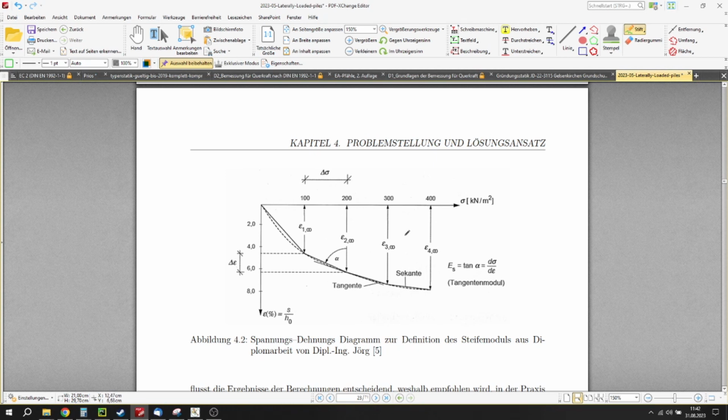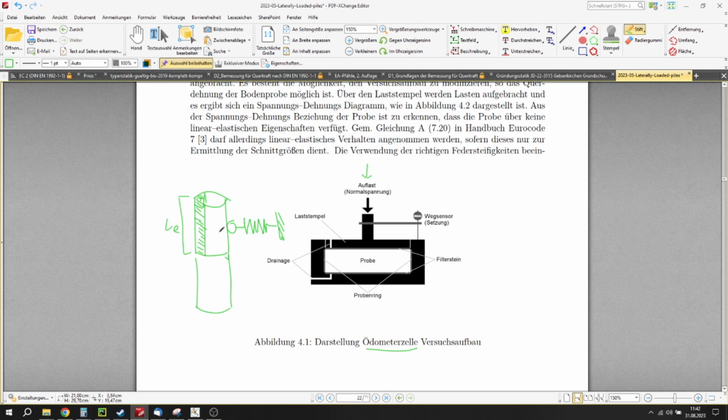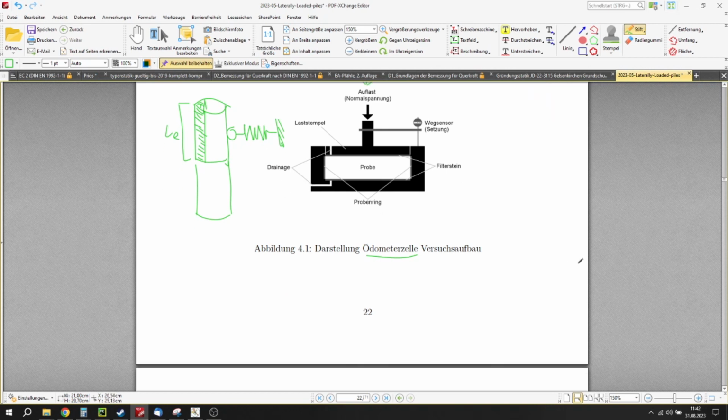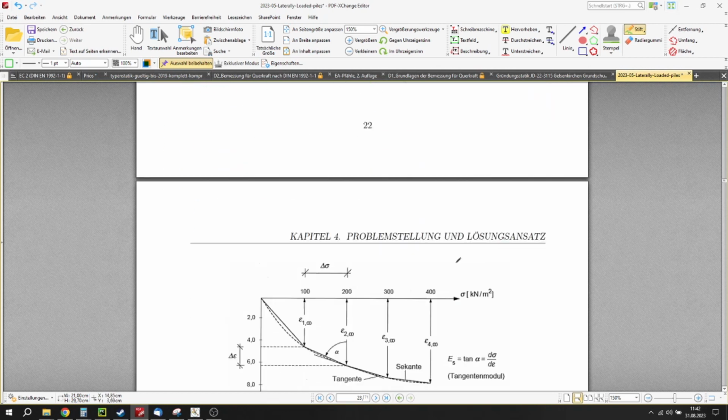And we can use this to our advantage, because this is literally what we're talking about when we talk about horizontal displacement. We have this reactive body, we have the soil, and then we press the pile into the soil and we want to know what sort of deformation we have. The way that it will deform can be described over this elasticity modulus.